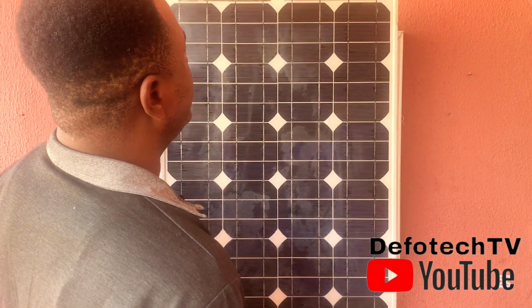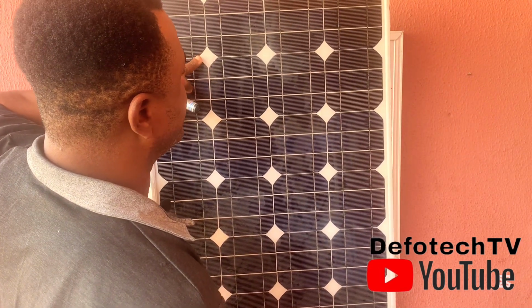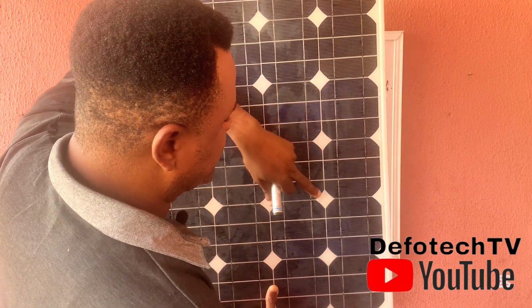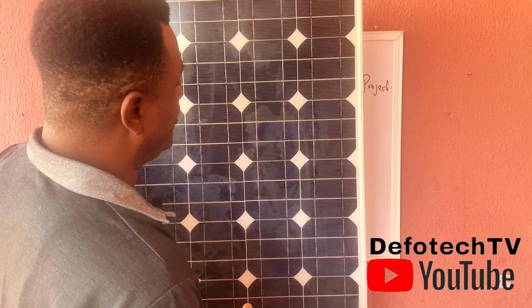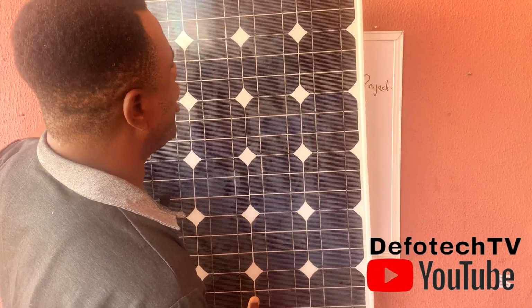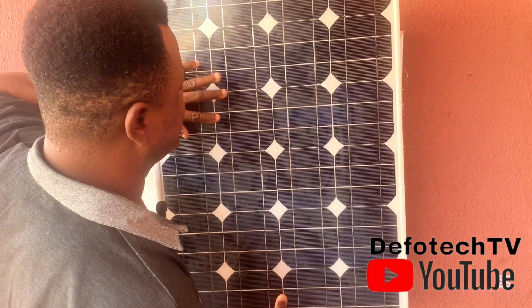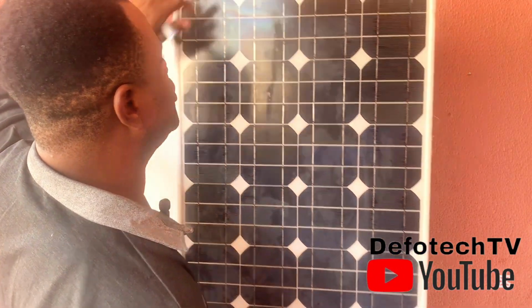Now, how do you identify a panel that is mono? You see this kind of diamond shape in between them. But if it's the poly kind, most times they're always blue, just straight lines all through. You don't have this diamond shape on them. So that's how you know the poly.